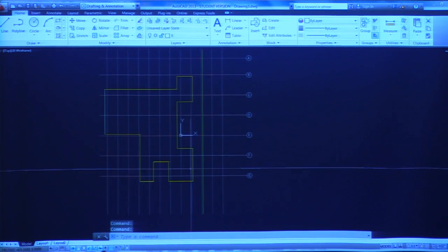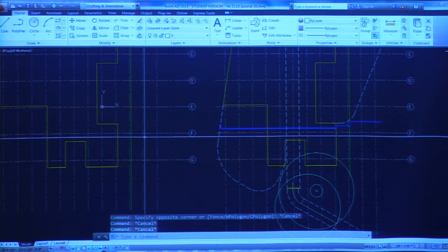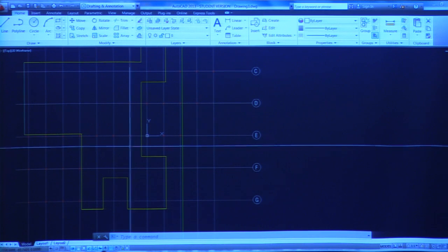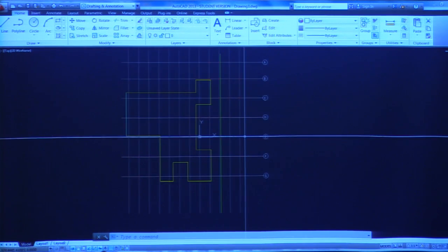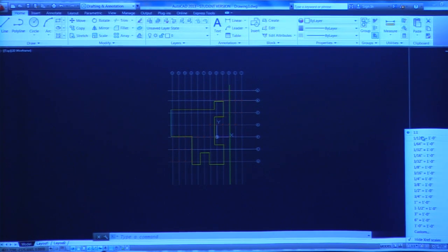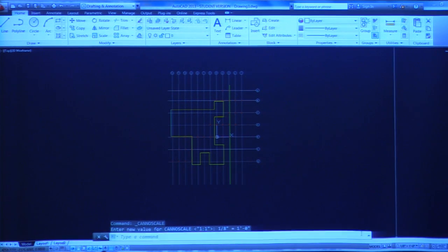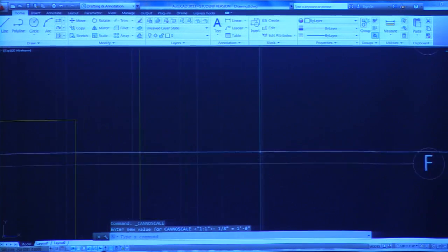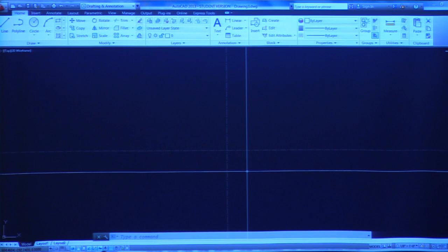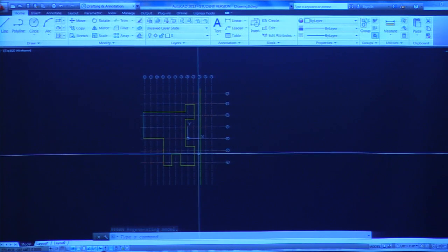One thing you'll notice too, if I flip between this file and the file I copied from, you see how the center lines are showing up properly here, and not showing up properly there? Well, if I zoom all the way in, oh my gosh, there they are. Awesome. But that doesn't do me a whole lot of good when I want to print this at a larger scale. There's a little interface here where you can tell AutoCAD what scale to display at. We've been working with our hand drawings at 1/8 inch scale, so I'm going to change that to 1/8 inch. So now it says 1/8 inch scale. That's great, but it's still not showing up. The other thing I need to do is type RE for regen, and that's going to redraw my whole screen. And now it's showing up properly. So that's great.